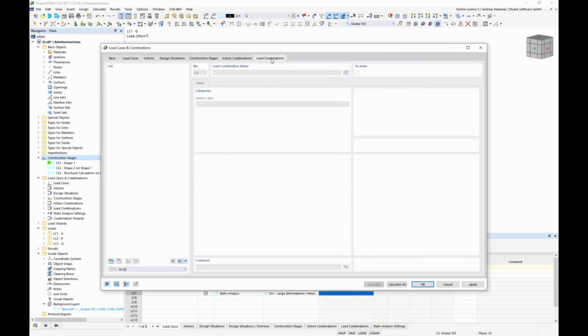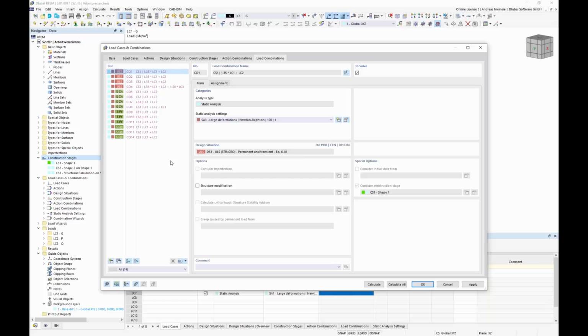And if we go back to load combinations, you see the list is a little bit longer, but now has a stages allocation. Stage 1, stage 2, stage 3. Here we have 2 combinations, the same for the characteristic ones. And as you see, we have now even defined stage 2 as basis and working on the element set of stage 3.